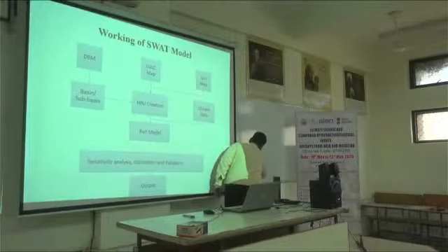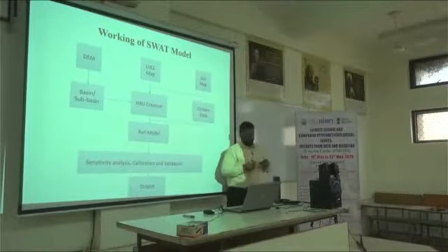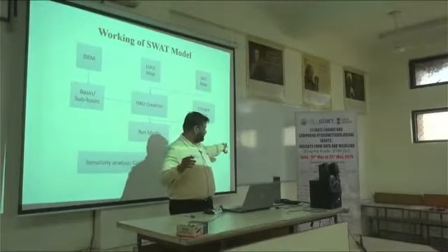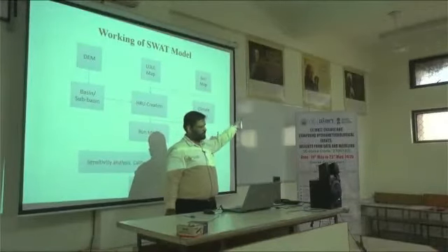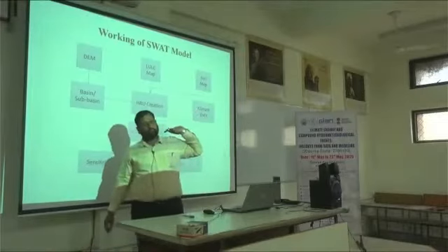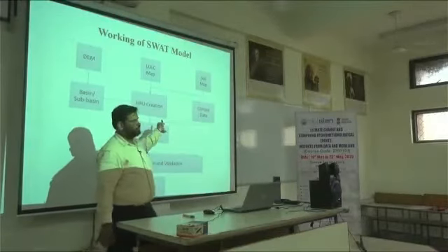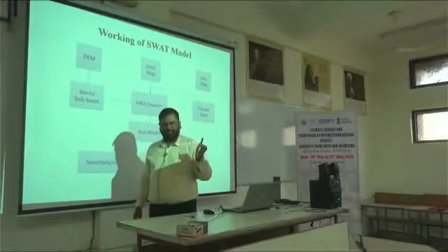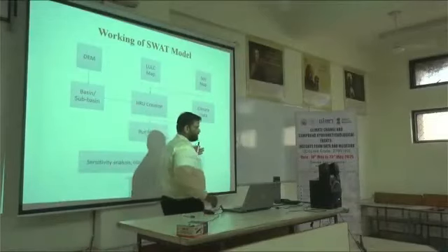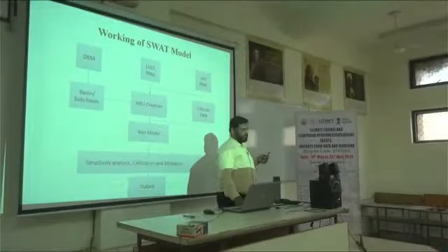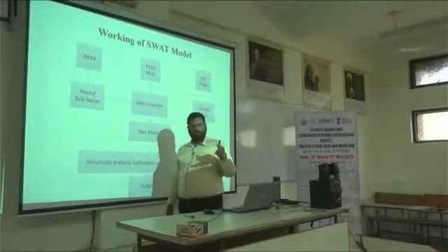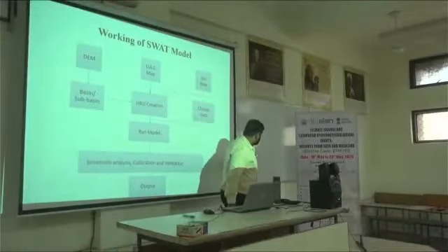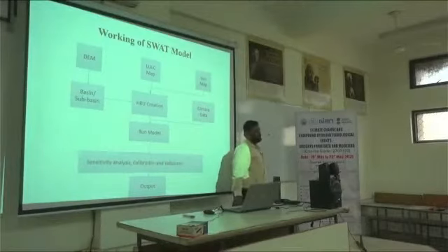Then the other data you require is your observed data. If you are computing the statistics between observed and simulated data with the help of discharge data, then your observed data would be discharge. You can also evaluate your model output with the help of evapotranspiration data, or satellite data; you might have heard of the GRACE satellite, which also provides soil moisture data readily. So if you have soil moisture data, evapotranspiration data, or groundwater data, you can do calibration with the help of these observed data also.